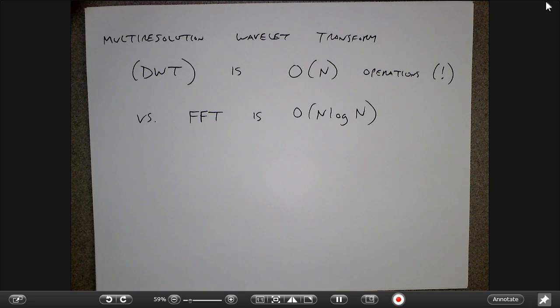And another argument for why we still might want to do wavelets is we should still be concerned about the amount of processing it takes at the receiver side to reconstruct the signal, right? So if I can reconstruct the signal with an order n decoder as opposed to an order n log n decoder, that will make my device much more efficient. It won't be buffering, but it will be quicker to reconstruct the signal. I'll need to buffer less because I don't need as much time to undo my processing, is one way to think about it.